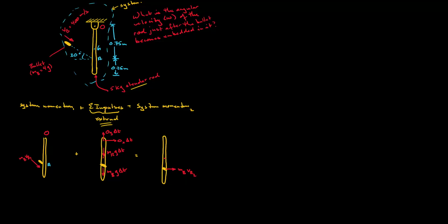And this is undergoing fixed axis rotation, right? So we're going to have a linear velocity at G. So I can call this the mass of the rod multiplied by the velocity of the center of mass at time 2. So that's my linear momentum. And I will also have an angular momentum, which we will call Ig omega 2. And this is what we're trying to find. We're trying to find this omega 2.